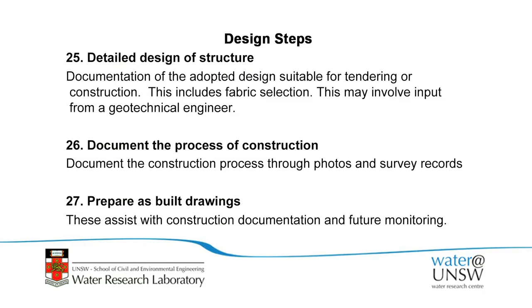So the better you document it, the more watertight it is if something goes wrong down the track, or if it's damaged and the damage exceeds what it was designed for, versus an argument about whether it wasn't built to design, or whether the conditions simply exceeded what it was designed for. So similarly, prepare as-built drawings. I'd always recommend that. They assist with documentation and with future monitoring as well.